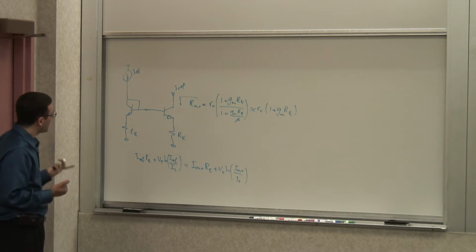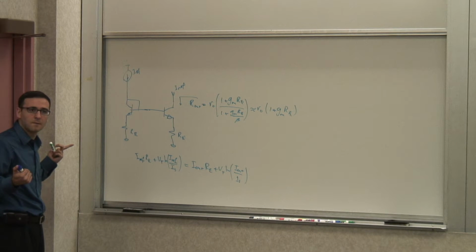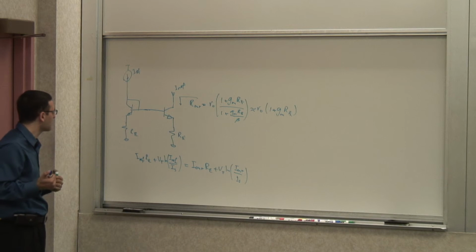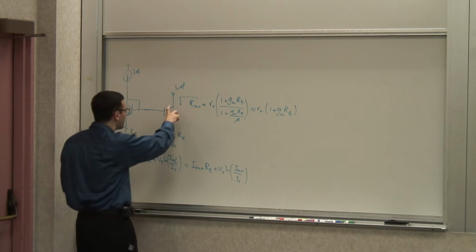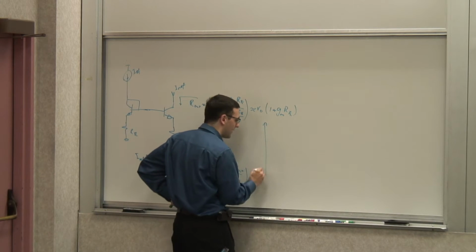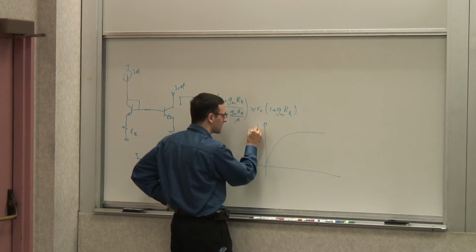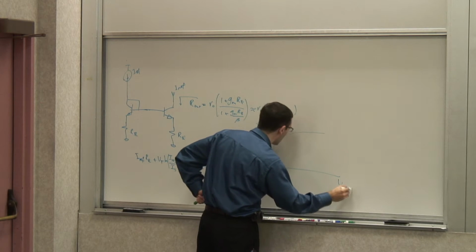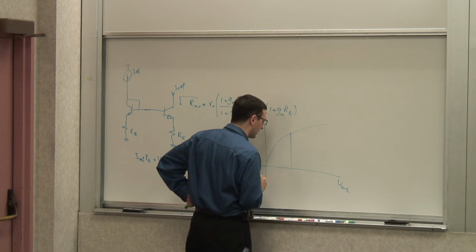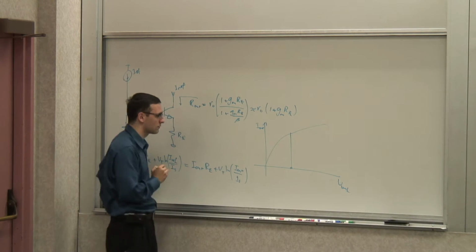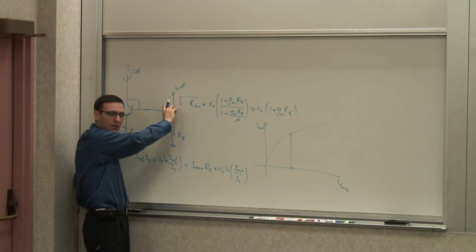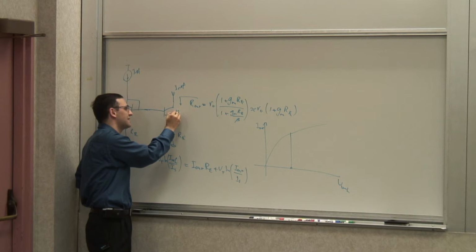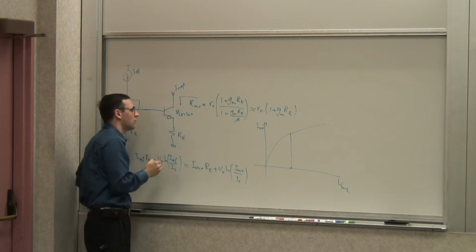So this is one way of getting a higher output impedance. And I can increase my output impedance. What is the price I'm paying for something like this? The headroom, the minimum allowable voltage. So now if I look at the I out versus V out, it will start dropping at an earlier voltage. Where is that? What is that voltage? That's when this transistor starts getting into saturation. So that's when this voltage becomes, let's say, around VCE sat, 0.1 volts, 0.2 volts, this voltage.